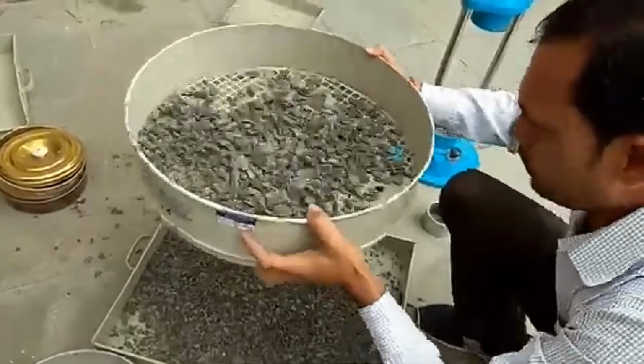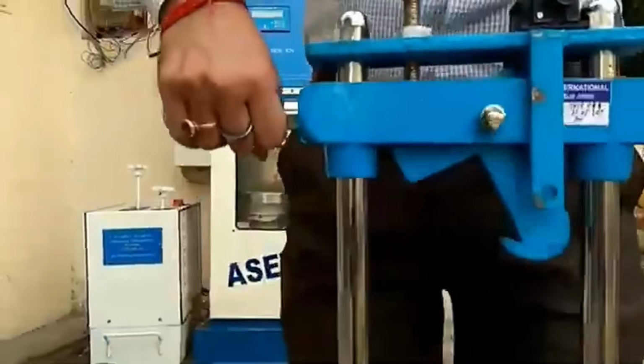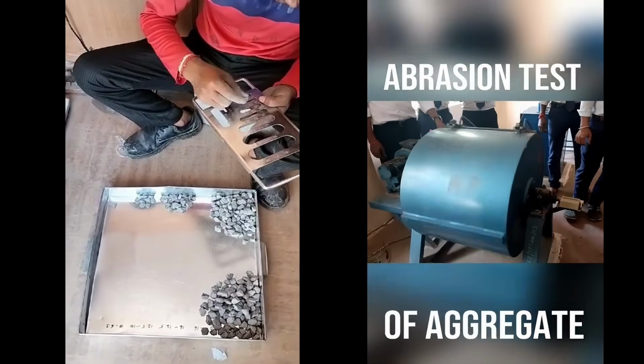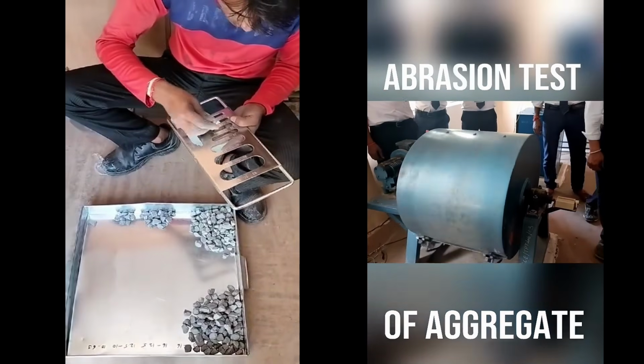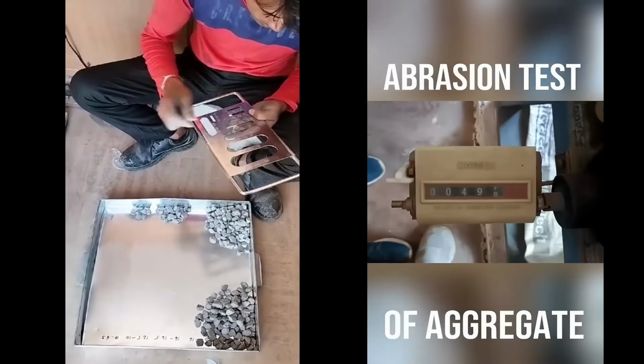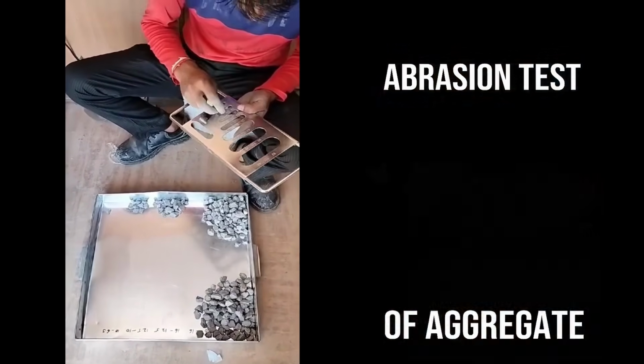The specifications for aggregates are as follows. Water absorption shall not exceed 2%. Impact value shall not exceed 27%. Flakiness and elongation index shall not exceed 35%. Los Angeles abrasion value shall not exceed 35%. The stripping value shall be a minimum of 95% retained.